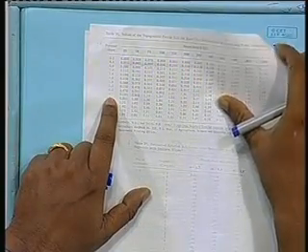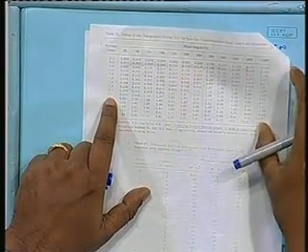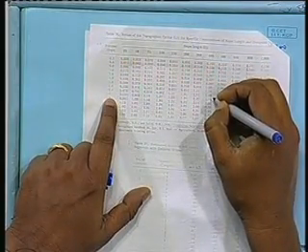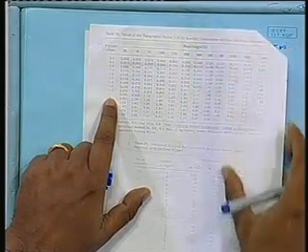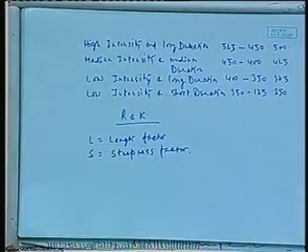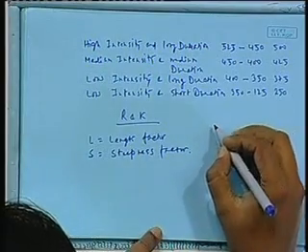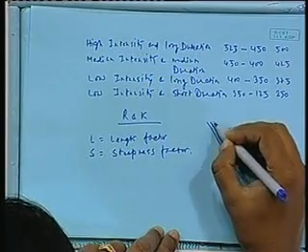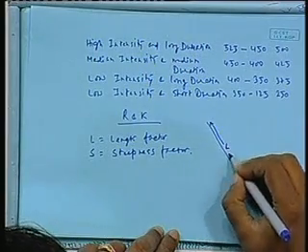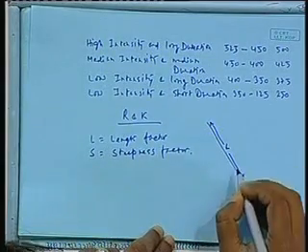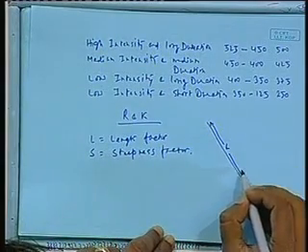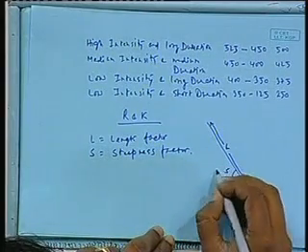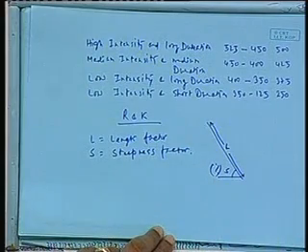Apart from this, there are a few other things to be explained. If L is given and S is given, you can find the value of L and S. If it is a uniform slope, you can find the L like this, and the slope S factor you can find from the percent slope. So from the percent slope you find the S factor, and then L into S.